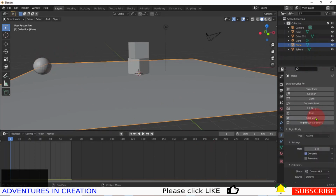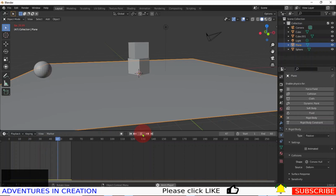So if we make the plane a rigid body, but we're going to make the plane a passive rigid body, otherwise the plane will just drop down in space as well. So we're going to make it passive, which means it is not going to fall down, it's just going to stay still. So now if I run the animation, the ball will fall down and stop on the plane. Great. So how's it going to hit those cubes, we wonder?